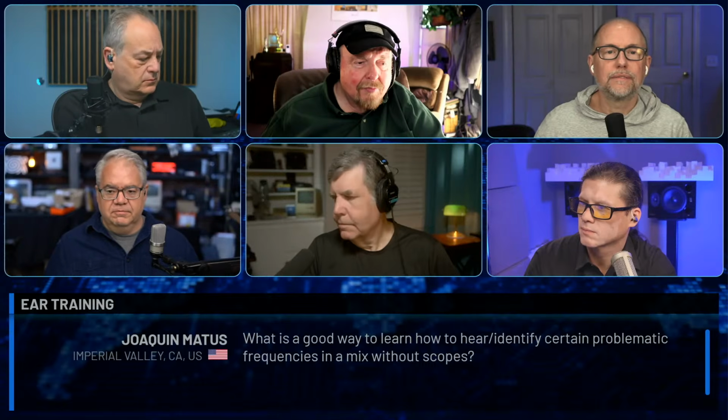Next question. Joaquin Mattis in the Imperial Valley, California. Up next, what is a good way to learn how to hear or identify certain problematic frequencies in a mix without scopes? Good, Jeff. So a great way to do this is to play your favorite music through an EQ and turn one of the parametric bands with a fairly high Q and a fairly high boost and sweep that around, and you begin to recognize those center frequencies.